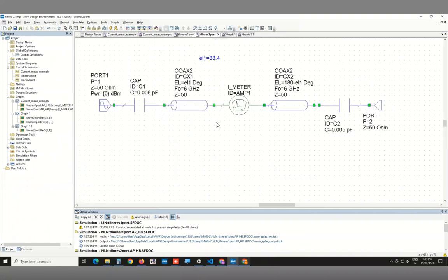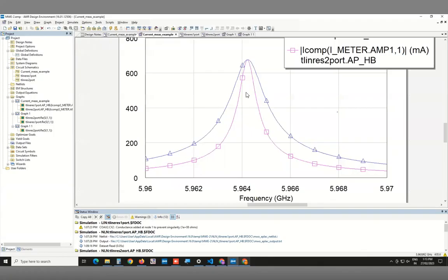The Q factor is different, the power is the same, but there is power leaking out of the other side as well. So you can maybe guess that for the case of the single port resonator, which has now become more strongly coupled, so it has a broader Q. Generally, when the Q is lower, the current you will get will be less for the same input power. The steady state doesn't build up to high enough power, right? So when you have a higher Q system, the energy will build up more.